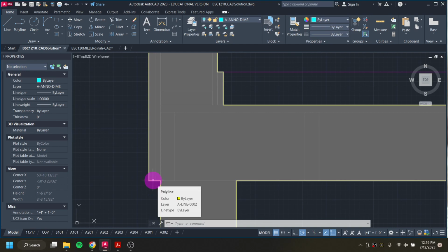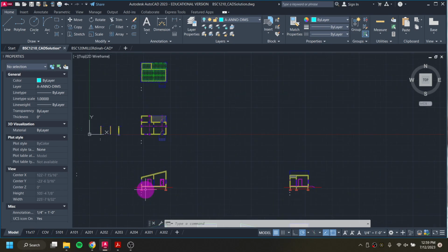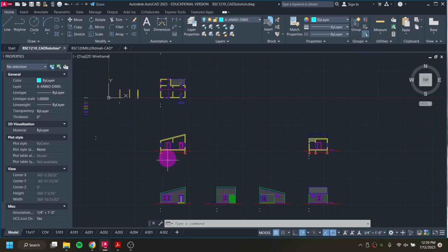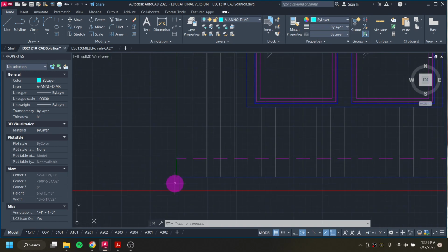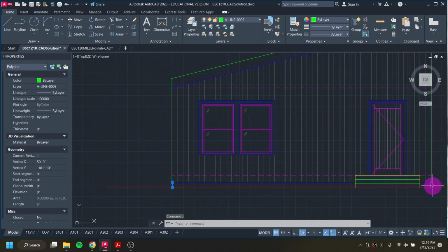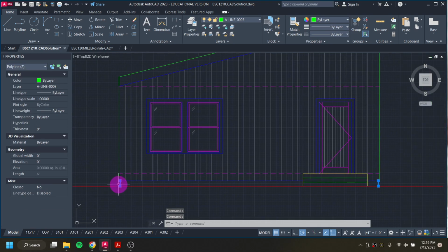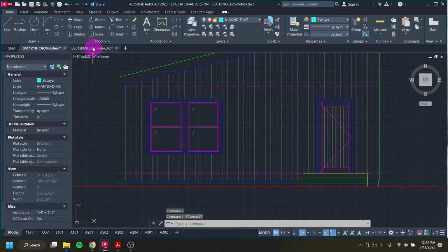I get a lot of the elevation submissions where the whole building is 24 feet, and then technically the elevation has been drawn too small. Our 24-foot measurement is coming from right here. So from here to here is 24 feet. So we can kind of start from there and then expand out, which is how I would probably approach this drawing to make it a little bit easier for myself of where exactly parts or pieces are sitting.